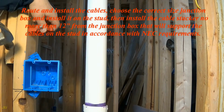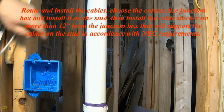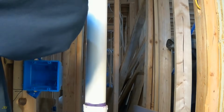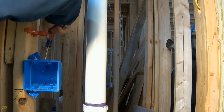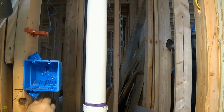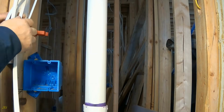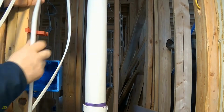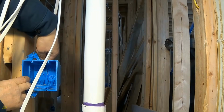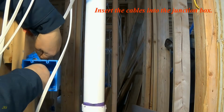Then install the cable stacker no more than 12 inches from the junction box that will support the cables on the stud in accordance with NEC requirements. Insert the cables into the junction box.